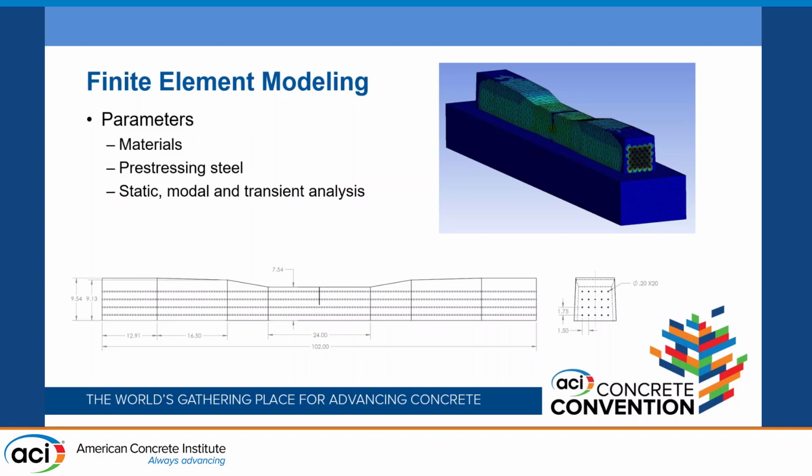We constructed our analysis using finite element modeling in ANSYS, defining materials from a paper which we will discuss a little more in detail in a second. Applied a pre-stressing state using the shown here array of pre-stressing steel wires, and then utilized a static, modal, and transient analysis to try to discover what is detectable in terms of vibration change with the cracks that we are inducing in the tie.